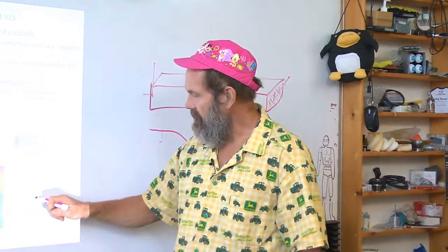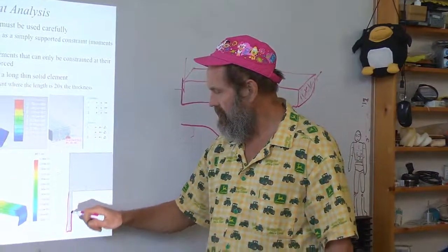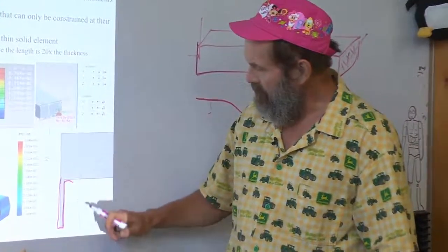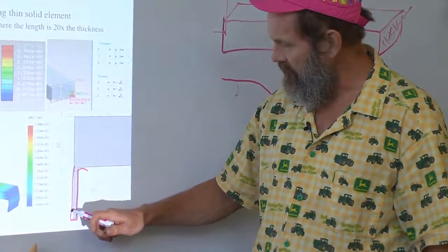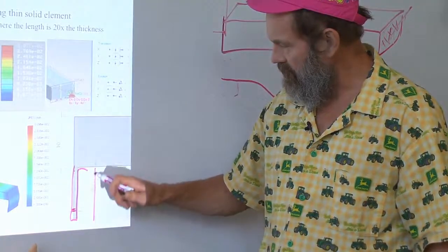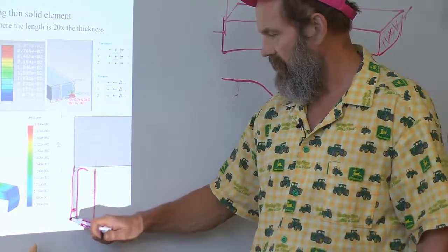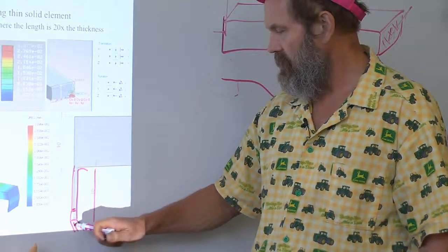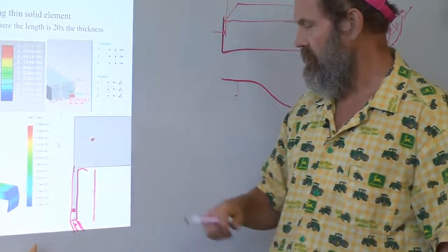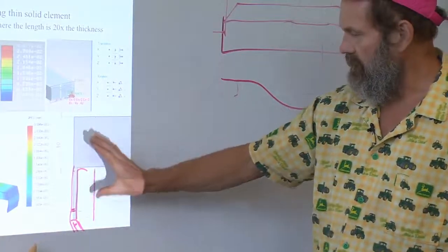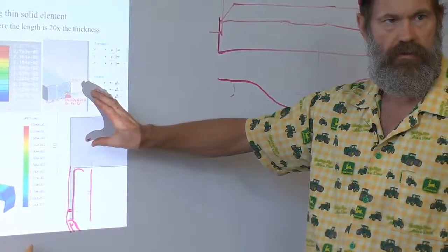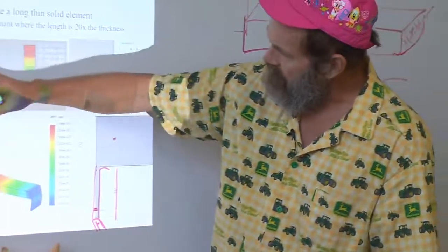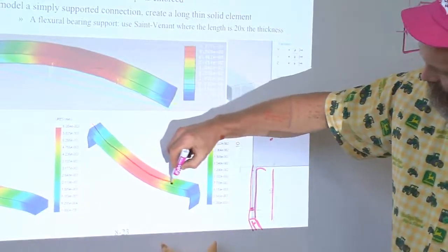So I can add this little tab here. But notice the proportions. This is 1 unit across. This is 10 units tall. So St. Venant says that if I anchor this here, this will not be able to affect this structure here with respect to bending. It will only provide vertical support. And now you see that the structure is, I'm getting the actual shape.